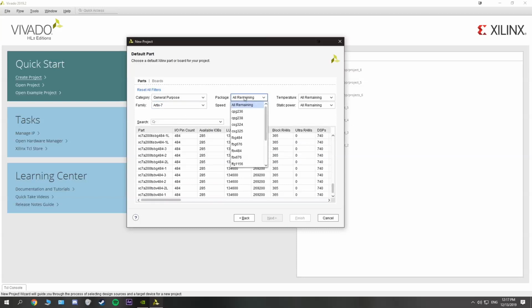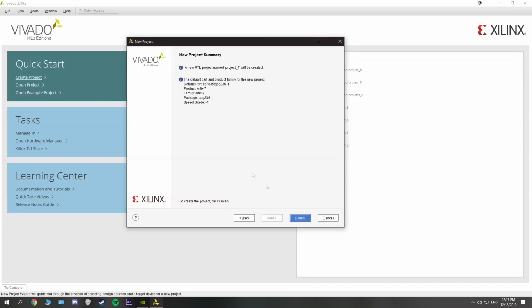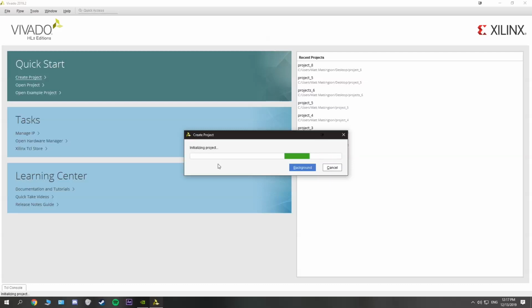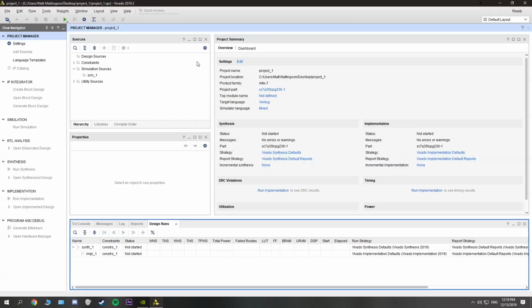And next you're going to want to choose your Basys 3 board. On the package it comes with, it should say which one you need, and you just have to select it through here. In this case we'll be using the XC7A35T 3060. So we just select all of this, and then this is the one that is equivalent to mine. It's not exactly the same, but it'll work for what we're doing.